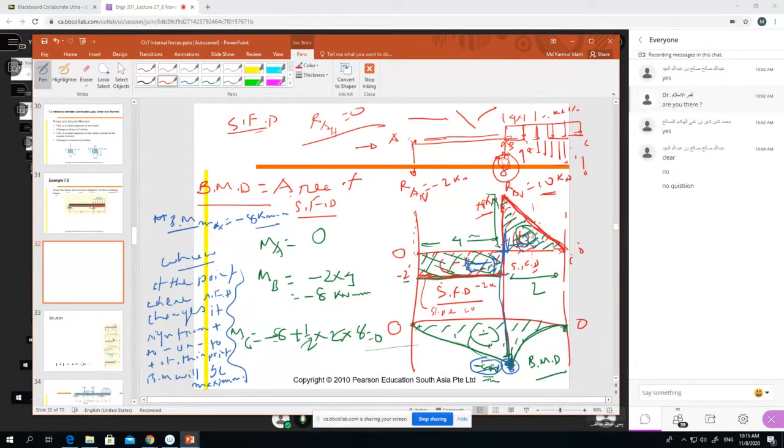That's why if there is no force, we go straight. If it is a distributed load, we go inclined down or up. If our force direction was like this, then we should go inclined up. Here we go inclined down, because every point is decreasing. So we go forward and we connect, and then we find it is actually a triangle. So, is the question clear?